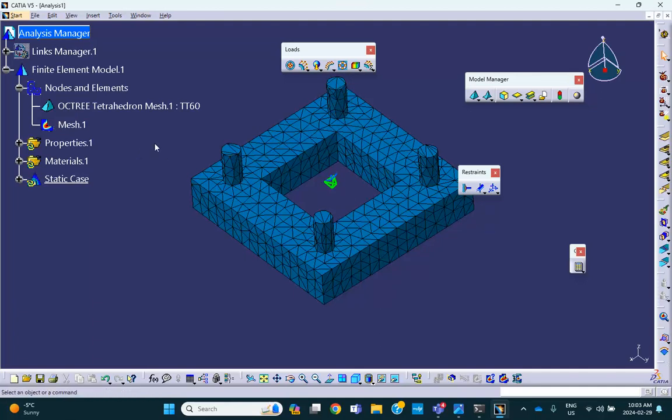So there are different ways of handling that thing. One is just make everything small, even down here. And the other one is just locally change these things. So let me actually go and do a local mesh refinement here.